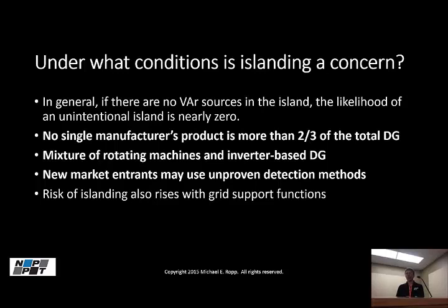I haven't seen a case yet where a 1741 compliant system became non-compliant just because of activating the grid support functions. I do understand that such cases have been observed in the lab, so it can happen. But the bottom line of all of this is that we do know the risk of islanding, the effectiveness of anti-islanding decreases when we add in grid support functions.